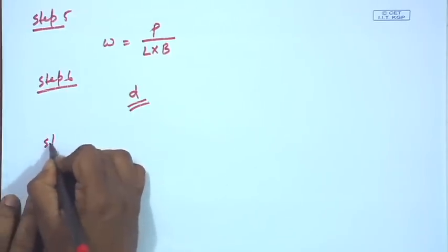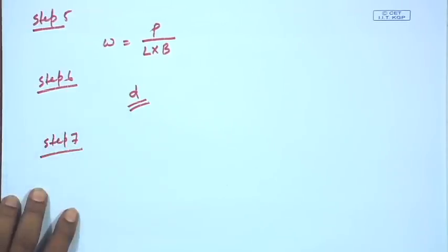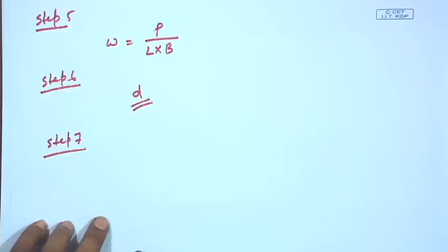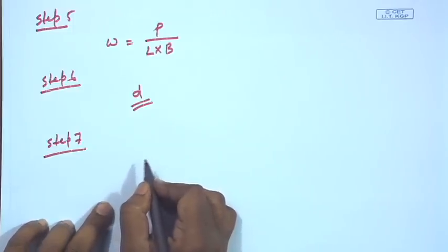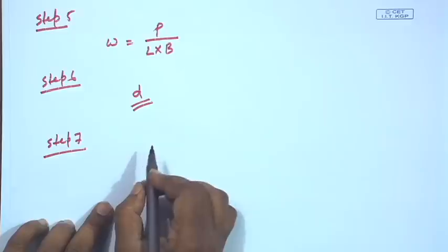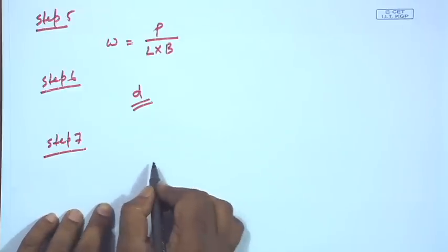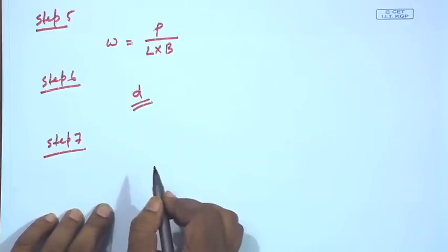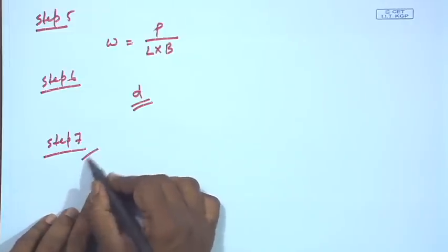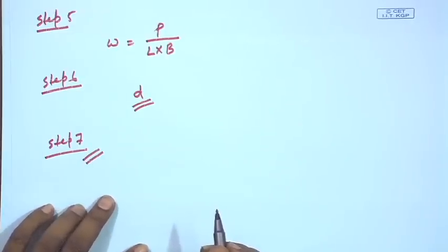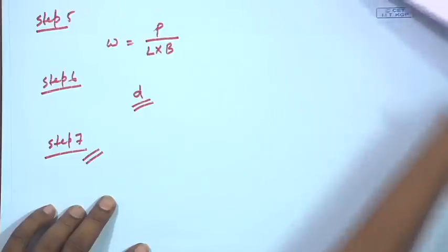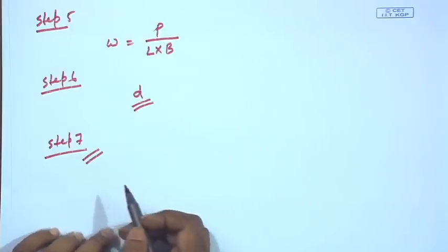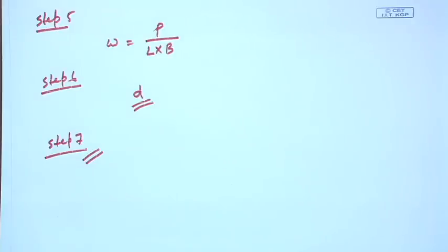Now, we will go to step 7. Holding down bolts, 2 or 4 in number and 20 mm in diameter, are usually provided to connect the two members. So, this is the nominal diameter and nominal number of bolts we provide. This is how one can decide the dimension of the base plate and gusset plate.